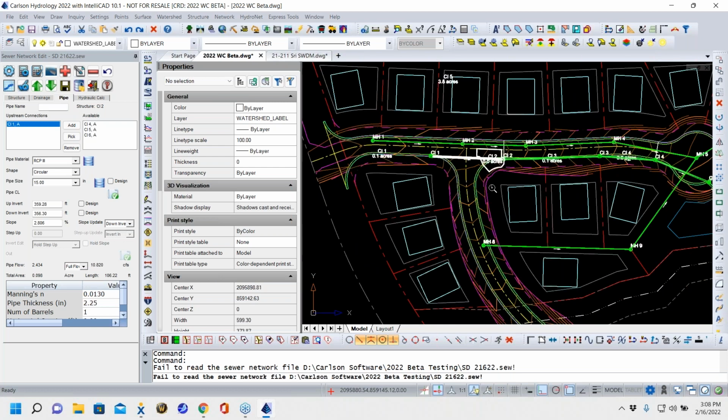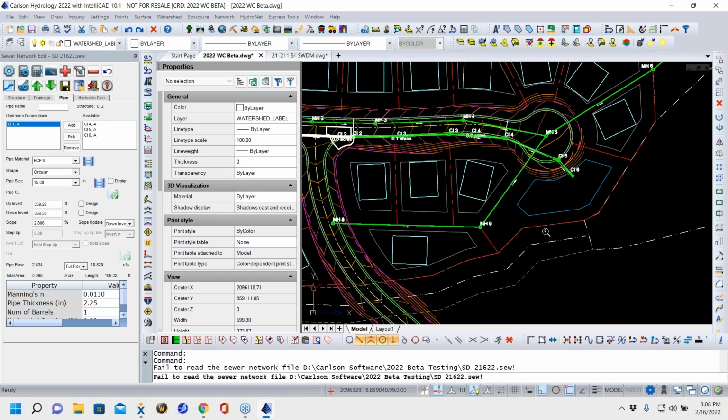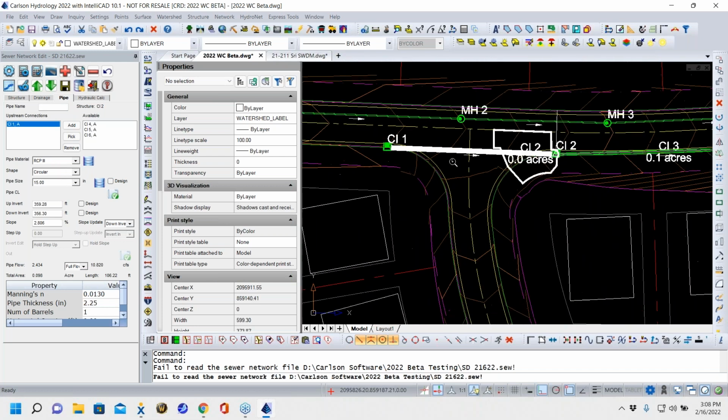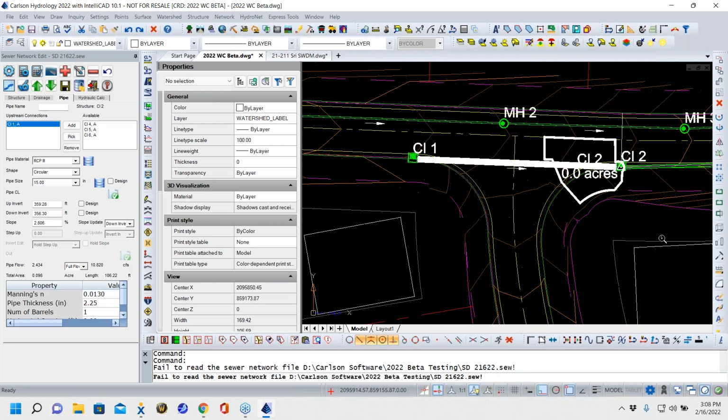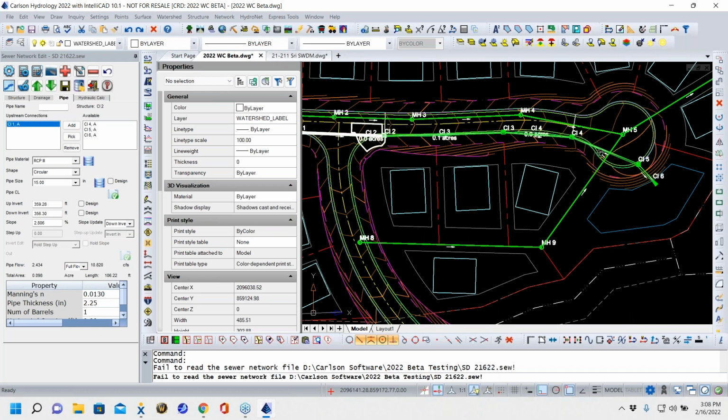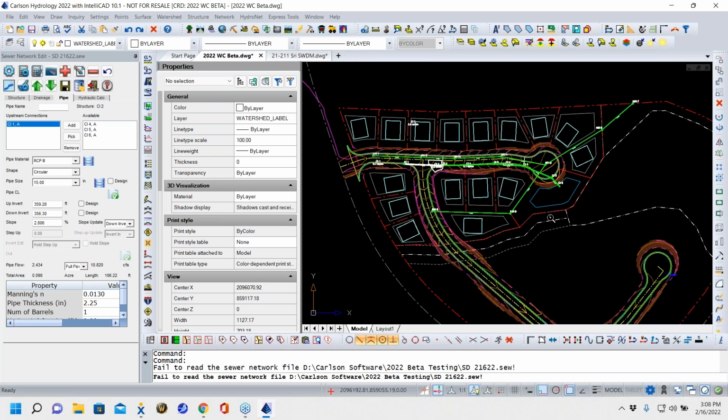The rest I just pick, do the drainage areas, set that first pipe slope, to 15 inch and get the material, everything you can tell it about that very first pipe, and then everything will adopt the previous settings all the way down. Okay, so that's actually how you can kind of design storm drainage.